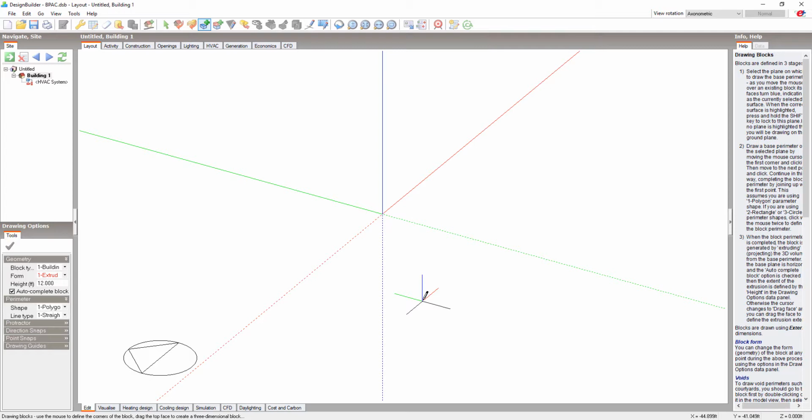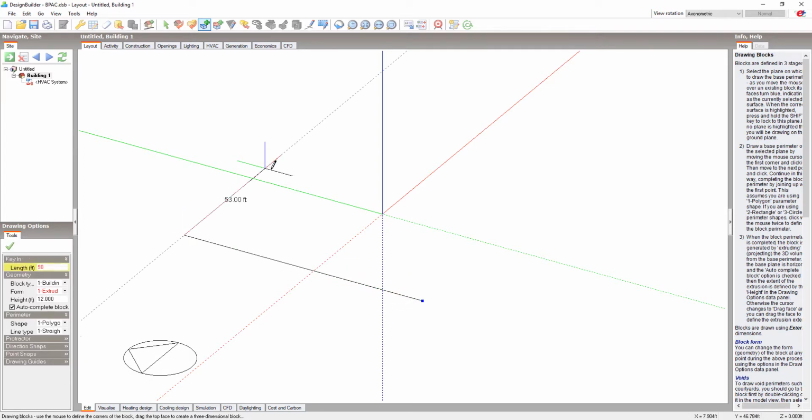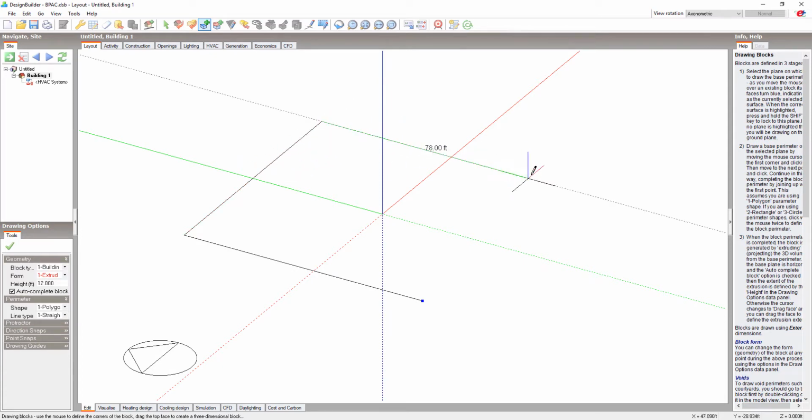You could create the model geometry by importing CAD plans and facade drawings in various formats, or import a 3D model from a BIM tool or from a GBXML file. I'll create the geometry freehand here. I'll start by creating a U-shaped block 90 feet by 90 feet.